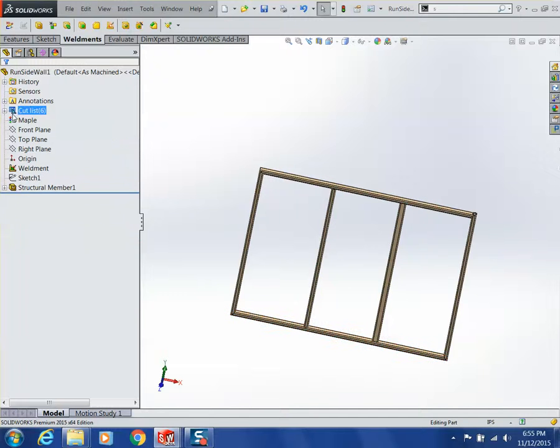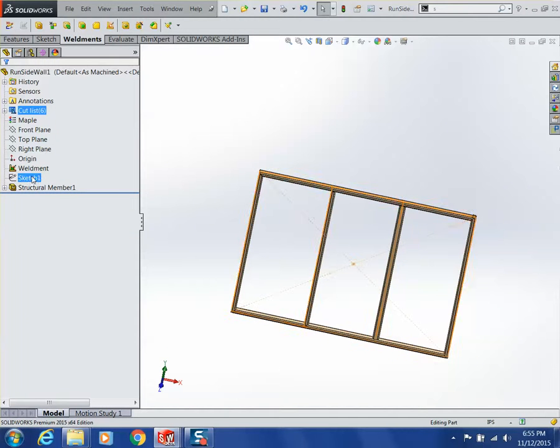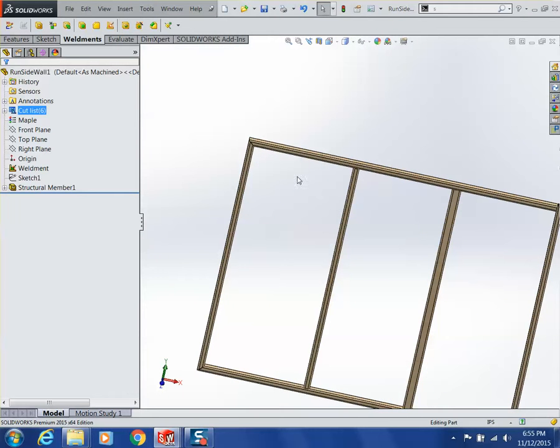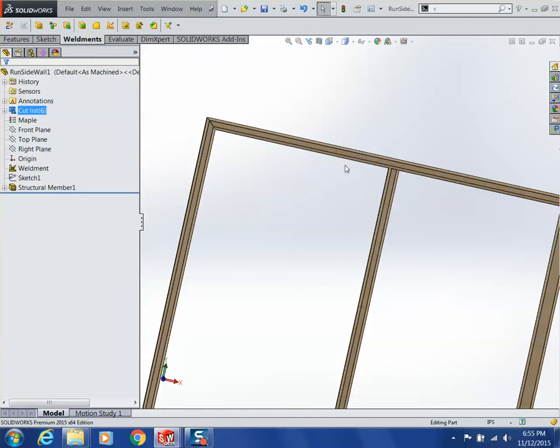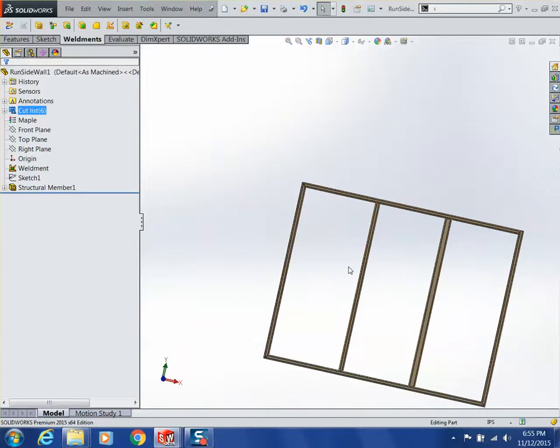So the other thing to point out here when you do weldments is it doesn't have to be one sketch, and it doesn't have to be all at the beginning. So now that I have this, if I want to do another sketch in here for a smaller frame that has to be inside here, but I want what's in here to be based on the size of the tube I pick, I can do another sketch in here and do another weldment right inside here, and keep going. The same way all this stuff happened in a 2D world, the exact same stuff can happen in a 3D sketch. It's just more complicated to make the sketch in the front, because 3D sketching can get a little needy sometimes, we'll say.